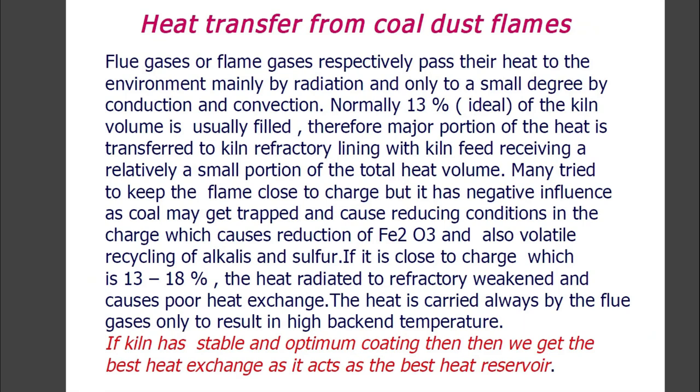Heat transfer from coal dust flames. Fuel gases or flame gases respectively pass their heat to the environment mainly by radiation and only to a small degree by conduction and convection. Normally 13% of the kiln volume is usually filled. Therefore, the major portion of the heat is transferred to the kiln refractory lining, with the kiln feed receiving a relatively small portion of the total heat volume.